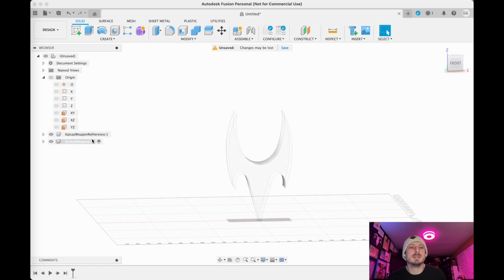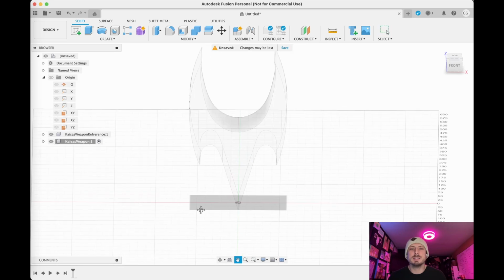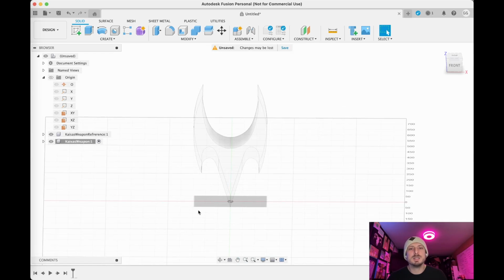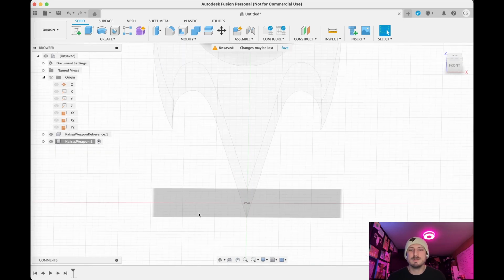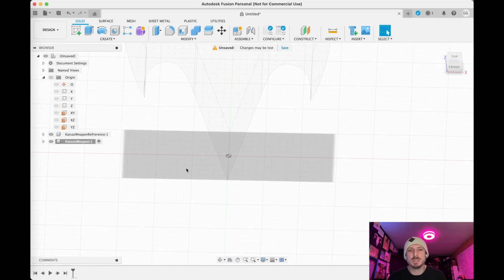It is at the same generation and automatically highlighted to be the current active component. So now we could go ahead and get started actually modeling this. Essentially, we're going to do this with a few lofts and a few sweeps. And we should have our model just about ready at that point. And then we could do some touch-ups.